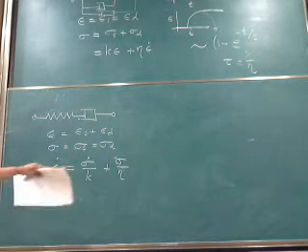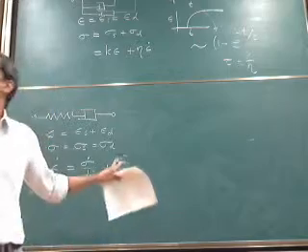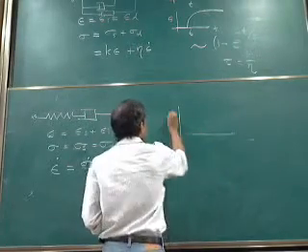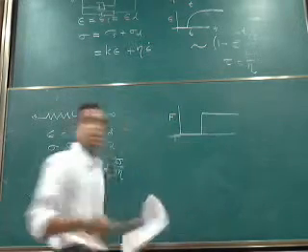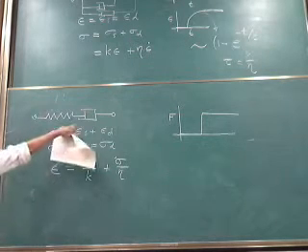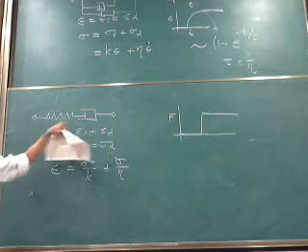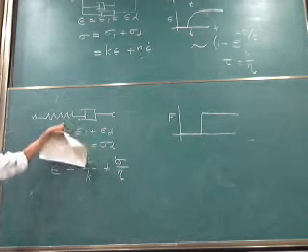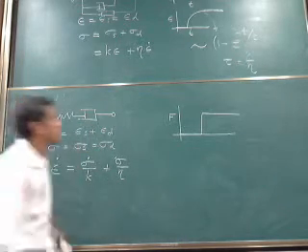And I can again ask, how will this material respond? Again, you can solve these equations to calculate the exact response. I'm going to give the solution picture here again. So I am again doing the same test. I am applying a step force to the material. And now you can see that again, the viscous element cannot respond instantaneously. The spring is going to respond instantaneously. So this element can stretch immediately, because the two are in series.